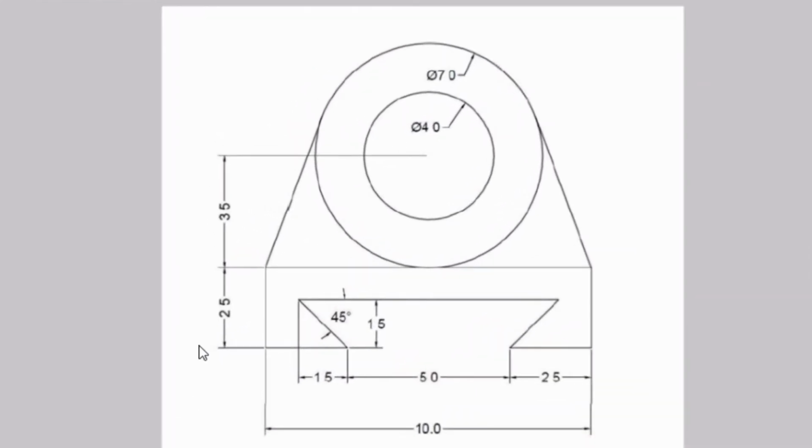Whenever you're seeing a sketch, you have to make sure from where you will begin, the way you're going to start the drawing and end the drawing, and how you're going to propagate. You have to plan the drawing. Even for this simple sketch, I have a plan. I can see a rectangle over here. I'm going to draw that rectangle first and then these two circles. I have a circle here, circle number 1, and another circle, let me call it circle number 2. And there is a tangent line connecting the circle and the corner of this rectangle.